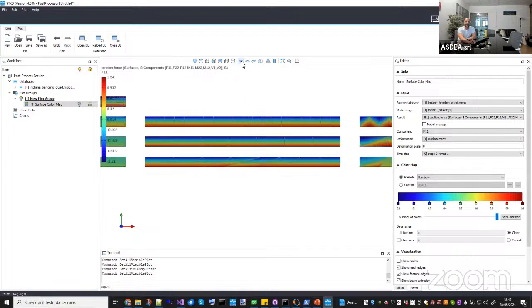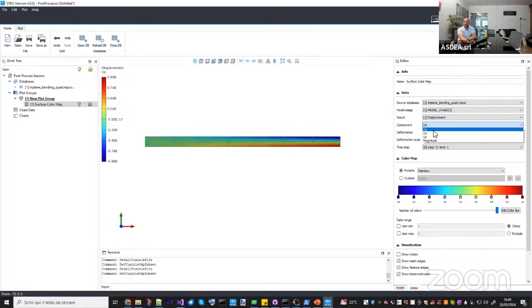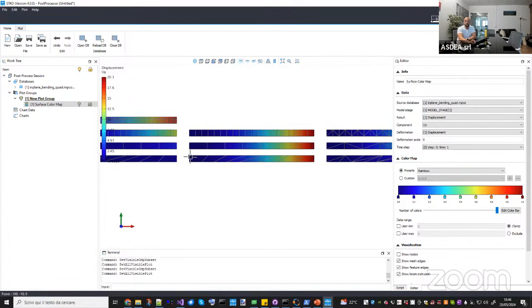If I add in-plane distortion, only aspect ratio distortion, sorry, the solution is still almost close to the real solution. There is an error of 2 over 1000, okay? So it's very, very small, 0.2% in terms of stresses, and the same thing applies for displacement. Actually, the stress converges slower than the displacement, but the error is very small. Now, when you add this one is where you can have problems.